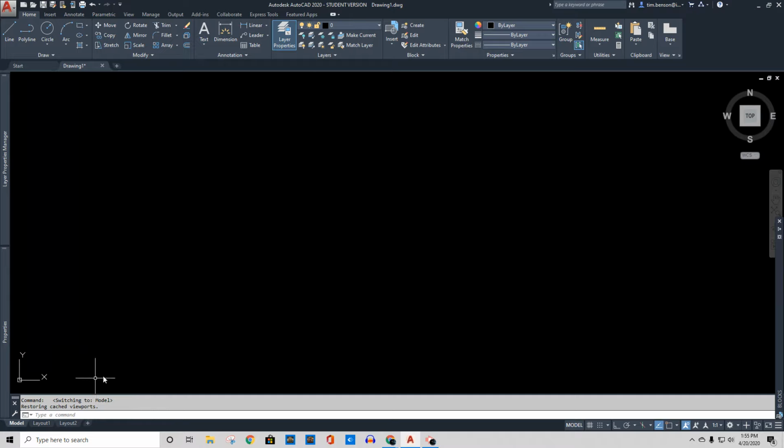Now, what you're going to find out really quick is this. Your drawing space is here, but it doesn't matter where I'm at up here. If I type anything, I want a line, I type line, I hit enter. Notice what pops up down here is what we call the command prompt line right here, command. And it asks me to specify a first point.